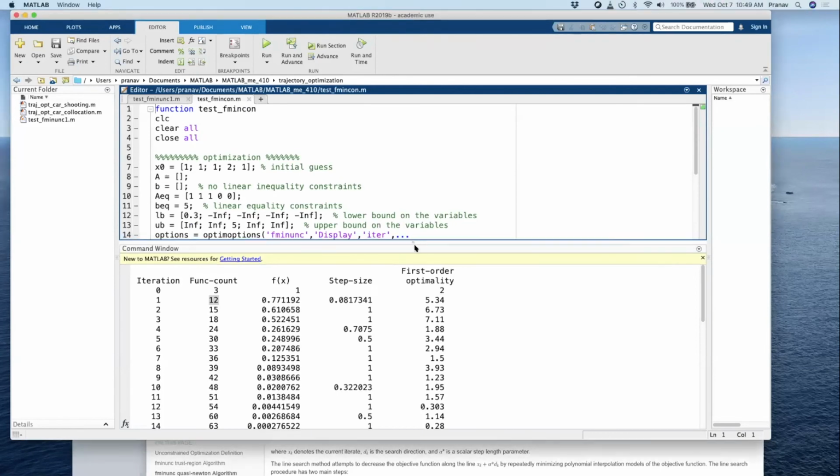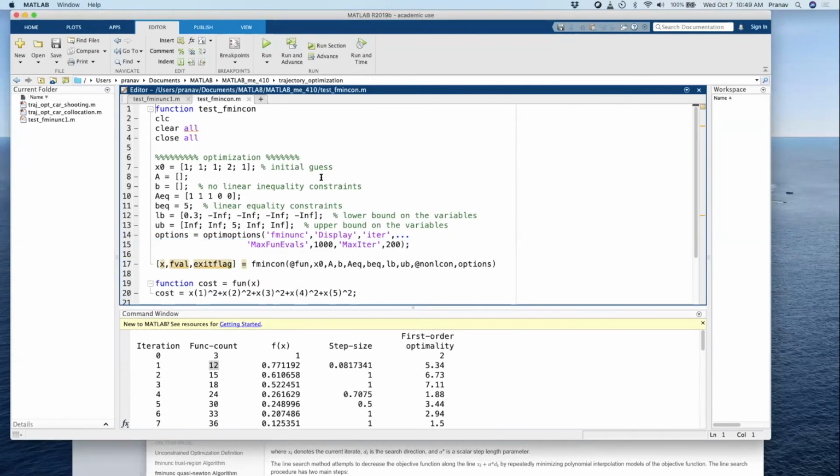So essentially the framework is exactly what I've written down. There's a call to fmincon, and fmincon has these arguments: the initial guess, which is some random guess, but it needs to be 5 numbers. There's A, there's B, the equality, and then I told you there's no linear inequality constraints, so that's just the null matrix, and then Aeq, Beq, and then we have the bounds, lower bound, upper bound, exactly what I put down there.